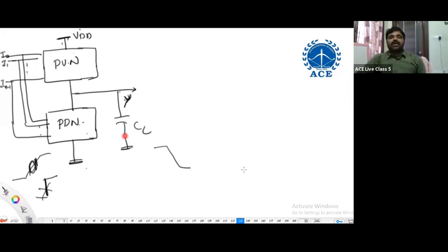So always in these logic gates, there is a capacitance. The capacitance has been charging or discharging. The chargings and dischargings are taking some time. That's what we have considered as a propagation delay. So far, we have discussed propagation delay. Charging and discharging through the on network is not in zero time. The time required to charge and discharge, we consider as a propagation delay.